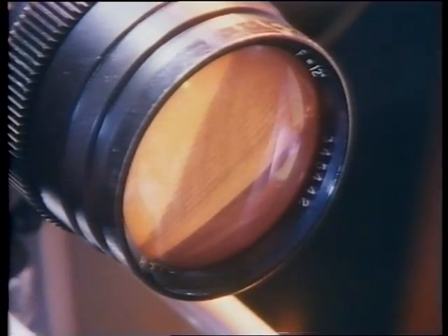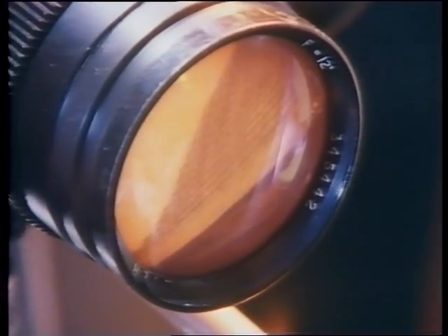An essential property not always associated with glass is fire control. This is Georgian wired glass, manufactured by the continuous rolling process. Wire is actually laid on top of a molten layer of glass. Then, after passing through another pair of rollers, a second ribbon of glass is rolled on top of the wire, which is now sandwiched in the center of the glass. Georgian wired cast glass is a translucent or obscuring glass with a textured surface. It provides light penetration and privacy.